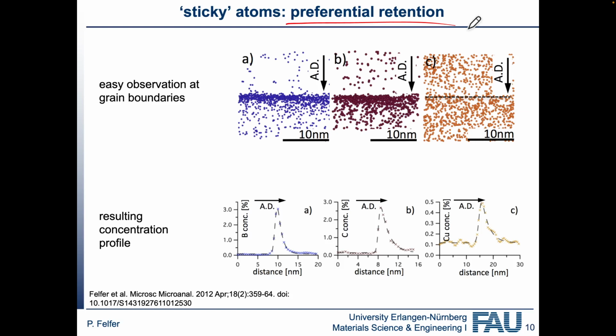which is unfortunately something that I discovered during my PhD thesis. Historically, when we were measuring a lot of precipitation in atom probe tomography, what happens in precipitation is essentially that atoms cluster together because they have stronger bonding, and the stronger bonding also means they become less mobile. But I started looking at a lot of grain boundaries, and in grain boundaries, the energy gain is more structural. An atom goes somewhere because there is a larger gap. It might not necessarily have a lot more bonding locally. It just might have a lot more space, and it might be a little bit harder to ionize than the surface atoms.